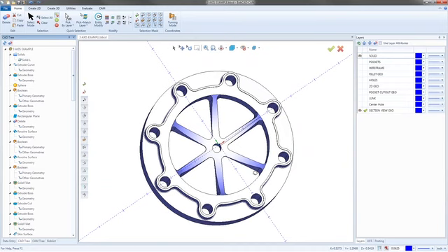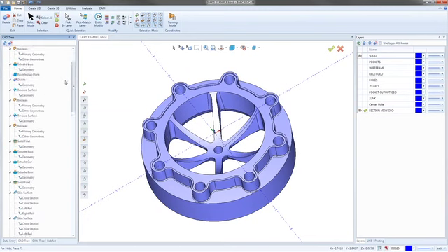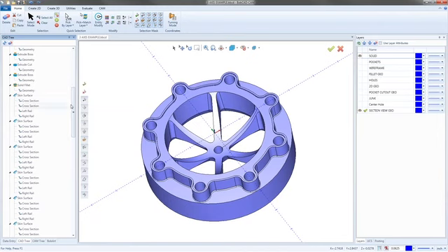The thing is, there's times when I want to machine everything all at once, and there's other times that I want to break it apart and separate as much as I possibly can. So when I rough, I want it to rough and cut these pockets in. But when I go to do this finish right here, this is just a sphere that got cut into the top of that shape. When I cut that, I'd rather that be one full clean surface that covers up these cutouts and everything.